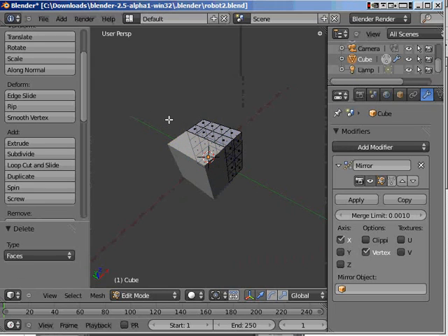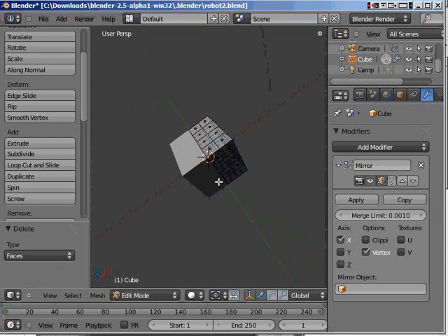Okay, we have got a mirror of that half there across, and it's along the x-axis. You know that sort of line that went through, like a pin stuck through? Now the other x side has been mirrored, and that's why it says x. Tick there. Right, now I want you to also go across here and click the clipping box.